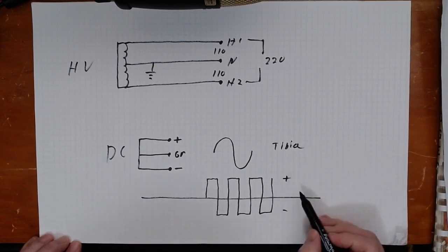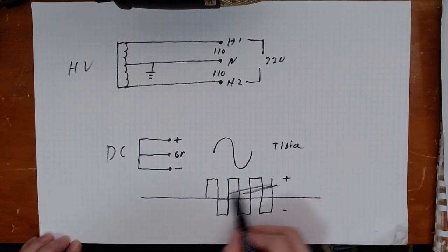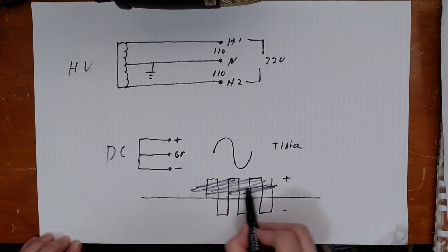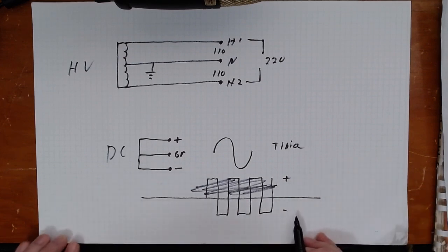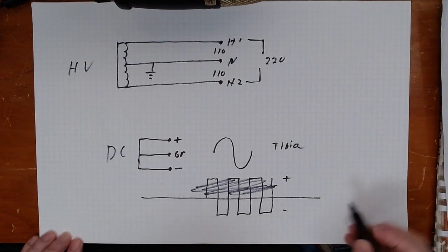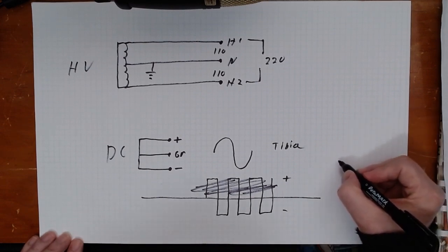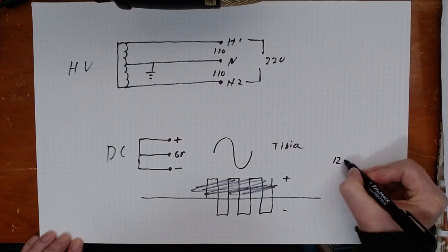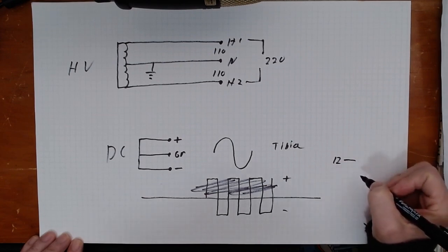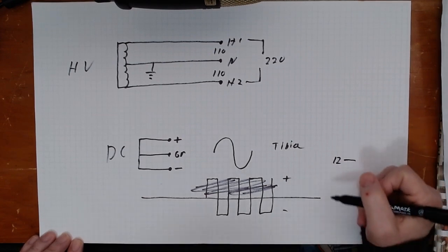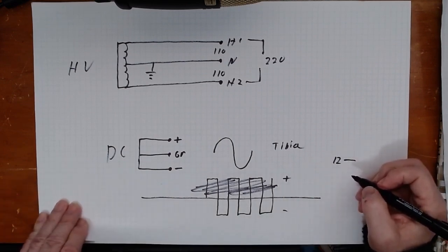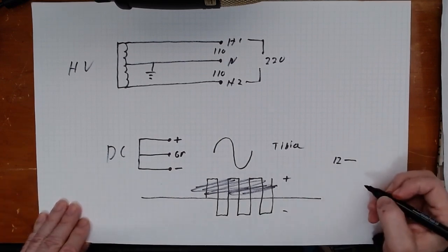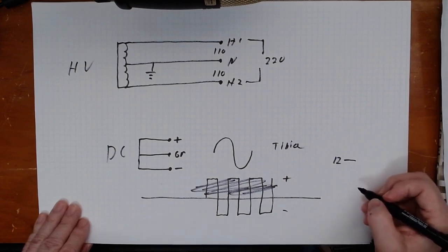But in the circuitry, a diode cuts off the positive side, leaving the negative square wave to pass through to the keying circuits, which are keyed from a 12 volts negative source. And this is why the orientation of the filter circuit, whether it's positive or negative, matters.